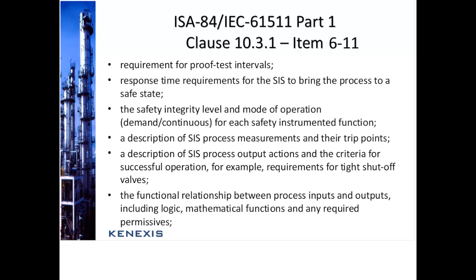A description of the SIS process measurements and their trip points. Is it a high pressure? It's a pressure measurement, and the trip point is where you have determined your process is out of control and you need to take the safety action. A description of the SIS process output actions and the criteria for successful operation. Again, with the fuel gas systems, that could be a specialized valve for tight shutoff with a very fast closing time.